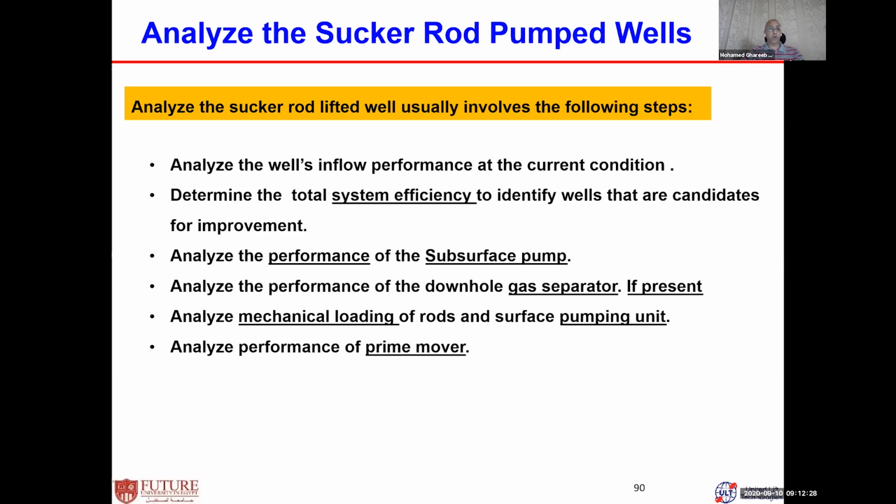For well and flow performance, I need to know the well test. I need to measure the flow rate and bottom hole flowing pressures, static reservoir pressures, and so on. I need to analyze this flow. But for the other, what tools do I need? For each type of artificial lift, there are certain monitoring tools, called monitoring and optimization tools.